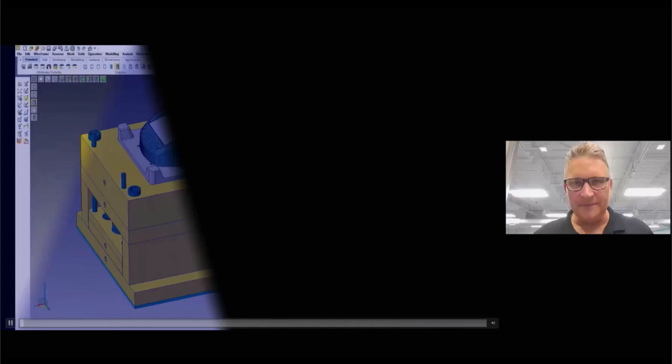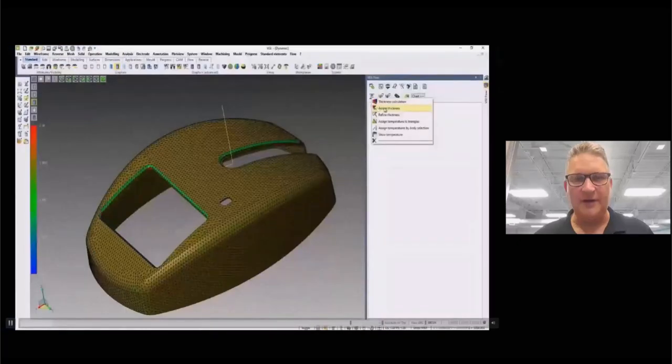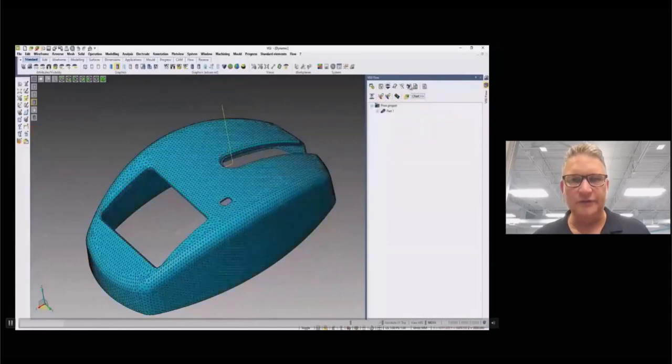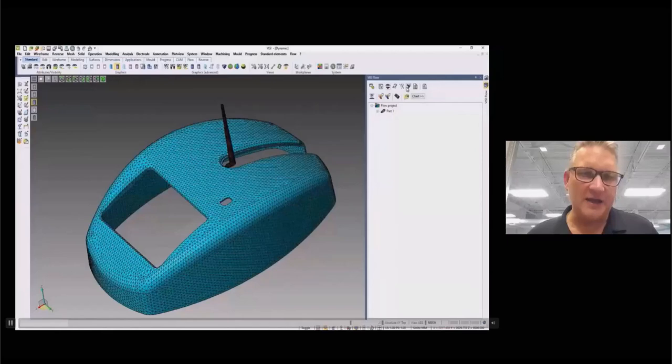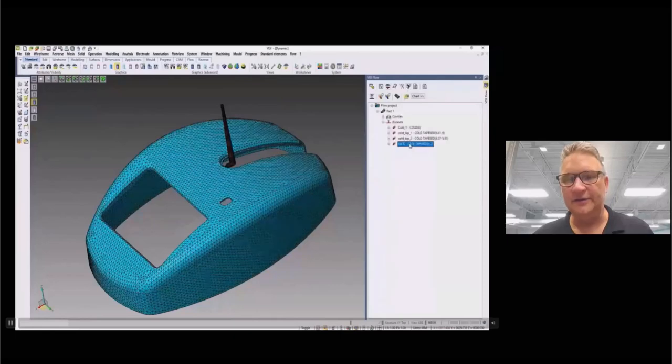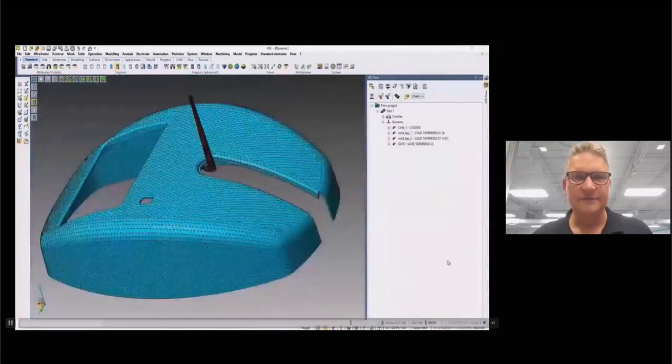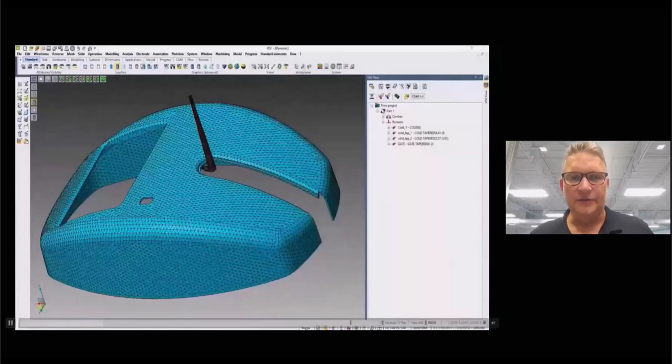this is going back through the thickness calculation and how you can assign the thicknesses. And once we're done with that, we'll go over to displaying your runners, gates, and then how I can modify or add different types of gating and different runner systems into the product, all by filling out these different parameters. And once this is done, this is where you can add a hot tip and define the runner gate assembly. And I'll jump to the analysis tab.